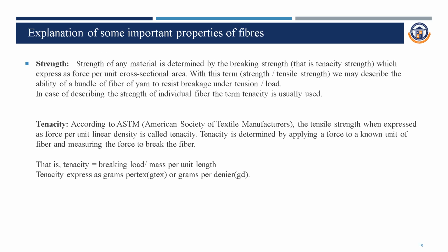Next we see about the strength. What is meant by strength? It is also called tenacity. Tenacity is defined, according to ASTM, American Society for Testing and Materials, as the tensile strength when expressed as force per unit linear density. Tenacity is equal to breaking load divided by mass per unit length. Strength is also defined as breaking strength, expressed as force per unit cross sectional area.